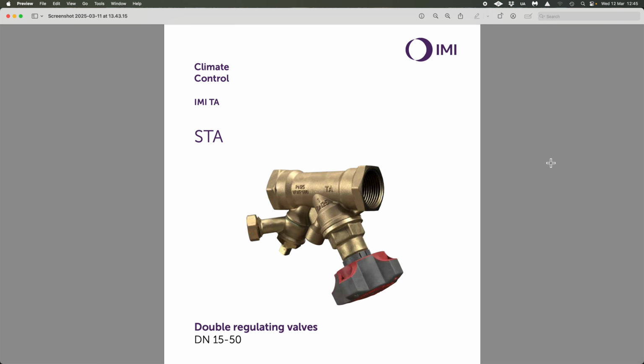What do we expect? But we were getting complaints from clients that were saying, "My water is tasting funny. I've had stomach upsets and all sorts of things after showering and bathing." And after we investigated, we realised that not only did we have a plethora of dead legs off of the main riser within this system, but about 60 or 70% of all of the houses, all of the flats, or apartments, in this block had capped off the low temperature tank fed water supplies, joined into the cold water drinking water supplies.